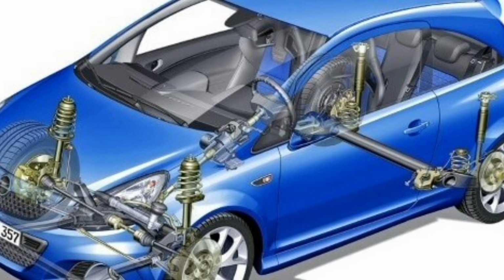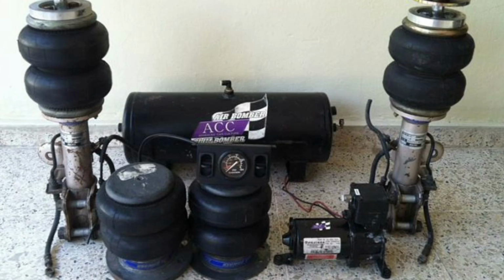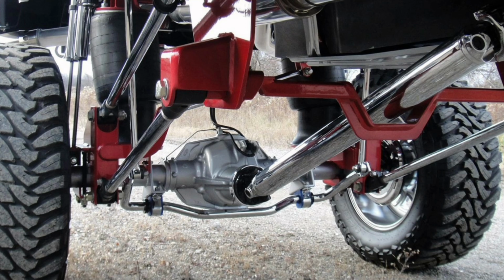1. Air struts. These are integrated into the airbags and help control the vertical movement of the suspension. The shocks can be adjusted to provide more or less resistance to movement, allowing more precise control of the suspension. 2. Electronic control system. Some vehicles may be equipped with an electronic control system that automatically monitors and adjusts the suspension. This system uses sensors to detect driving conditions and adjusts airbag pressure and damper stiffness to suit different situations.